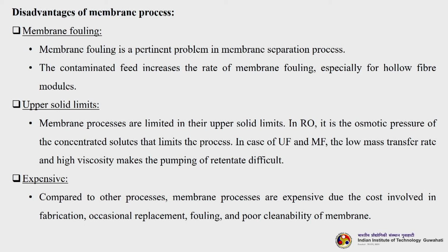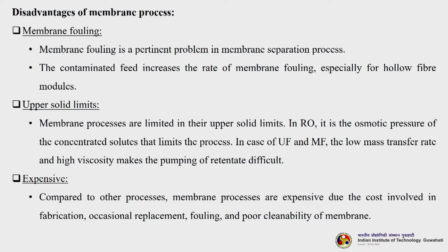As you understand, in the last class we discussed how fouling takes place. Fouling is a consequence of concentration polarization. Concentration polarization is the deposition of solutes over the membrane surface which happens gradually. When excess deposition happens, some of these solutes will try to squeeze themselves and get inside the pores of the membrane, thereby blocking the pore mouth as well as the constricted passage of the pore inside the membrane. Thereby causing two types of fouling, either external fouling or internal fouling. Then the next one is upper solid limits. Membrane processes are limited in their upper solid limits.